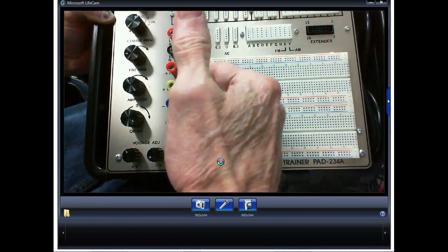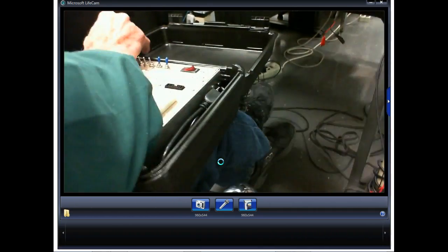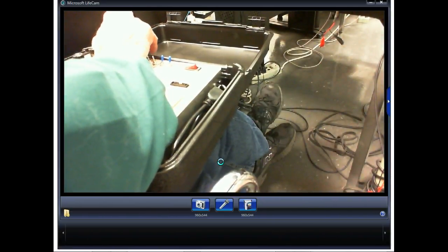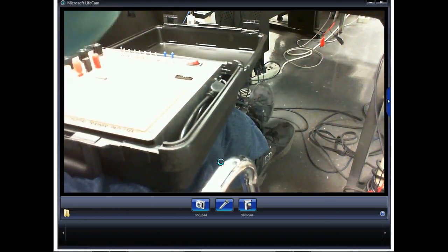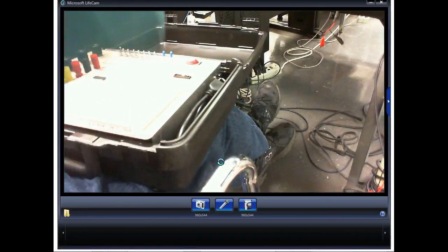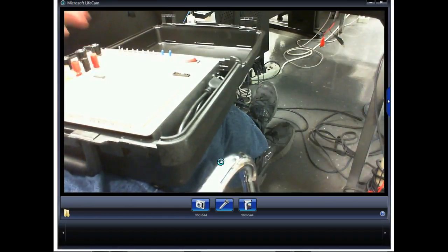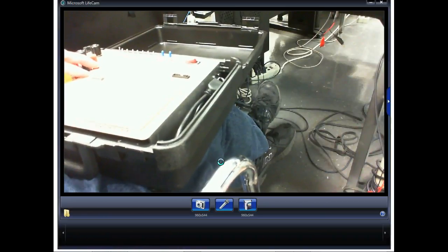and people don't understand that either. If you ever go look at a power supply, or if you ever go look at your house, and you take the panel off and look at the number of wires coming into your circuit breaker, how many wires come into your circuit breaker? Well, that's the back of your circuit breaker. I mean, how many wires do you plug into that thing? You plug in 1. You might have 15 plugs out there, but you plug in 1. Well, where did all those hots and neutrals come from? Well, they're jumped out at the circuit, right?